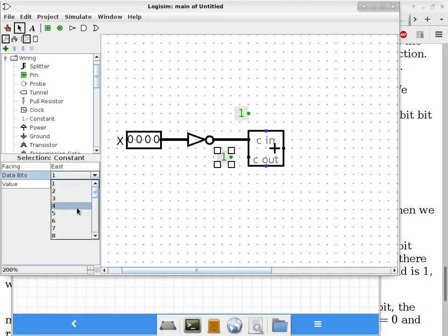And this has to match the width as well. And this is going to be the value of 0. So I'm adding the negation of x to 0, but I'm specifying the carry in to be a 1. That's the same thing as adding 1. Okay, carry in is your k0, which allows you to add that 1 extra, just by specifying a 1 for your k0.